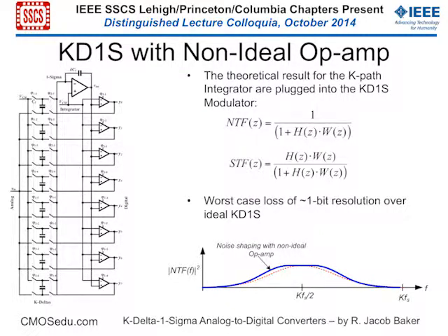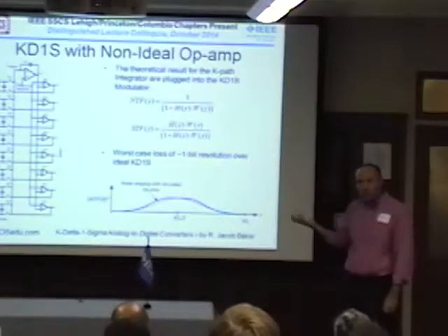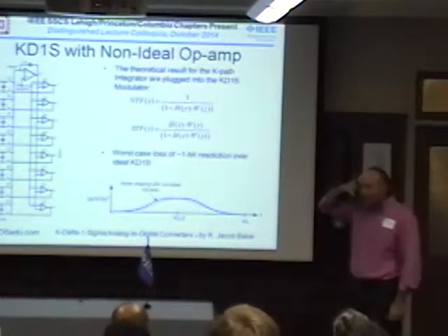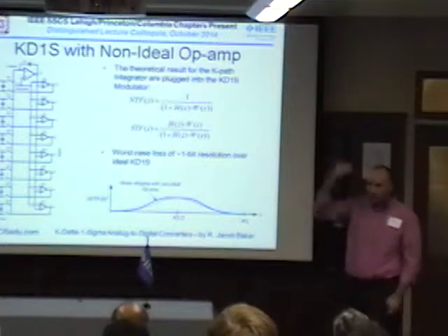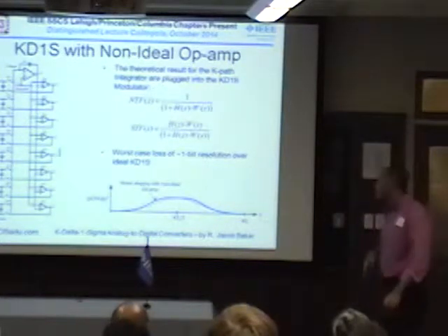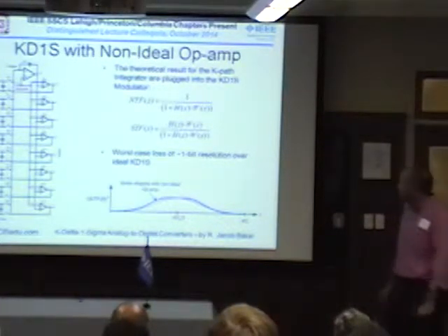You look at that and go, well, that's unfortunate, but you know what? It's not an error. It just says instead of my signal to noise ratio being 60 dB, it's 58 dB. It's not a catastrophic problem. It just means your performance is affected. It means I can't hear as far away with this data converter in this phone as I could with one closer. So it means it's manufacturable.